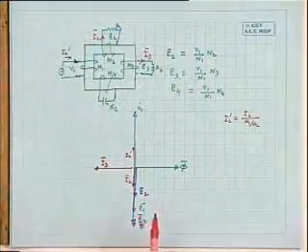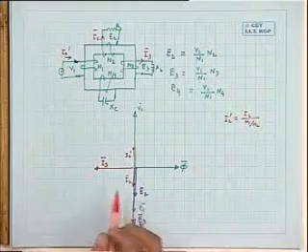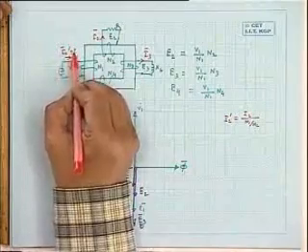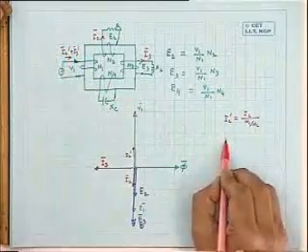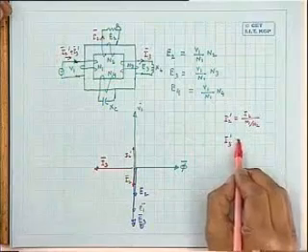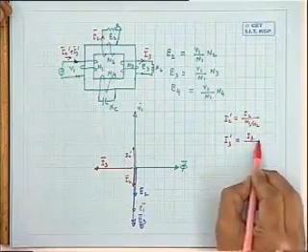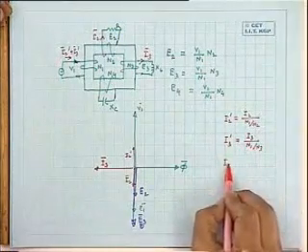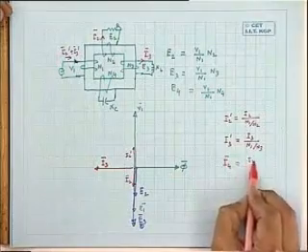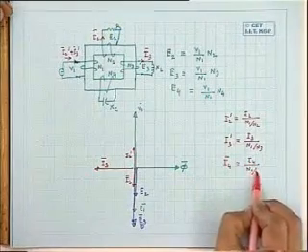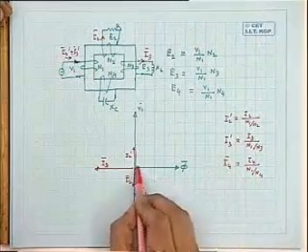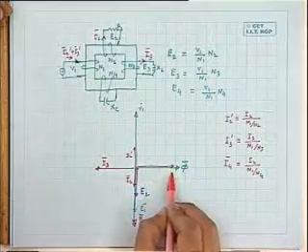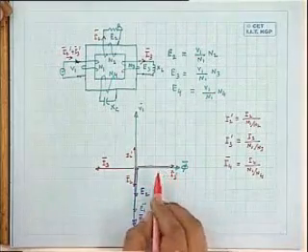How much will be its length will depend upon the magnitude of XL, etc. So this I3 once again will produce an I3 dashed here. So the magnitude of I3 dashed will be actual I3 divided by N1 by N3. And similarly, you can get I4 dashed, which will be equal to I4 divided by N1 by N4. So I3 will have a reflected part.